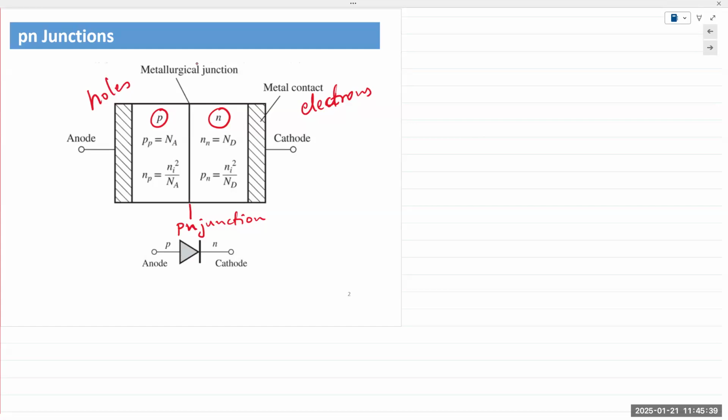So we had a cathode and we had an anode in a vacuum tube. It was a one-way device heated by a filament. And when you applied a positive voltage to the anode, electrons from the cathode would be attracted to the anode. You have a one-way current flowing through the device.